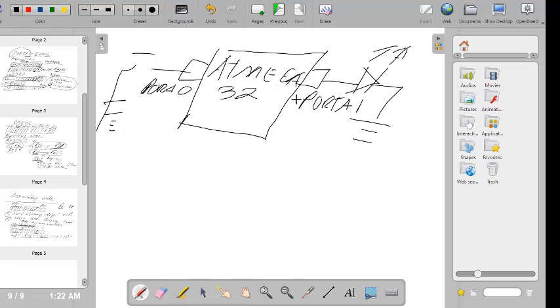Now you can see here that we've got two ports. One port is connected to a button, all right, and another port is connected to an LED. So now in this case, we know that this port where we are connecting the button benefits from being an input port, all right, because an input port is a port that takes in information, right? Meaning here when the button is pressed, we need to have a way of knowing that the button is pressed, so we'll get information from the button. And then this is an output port.